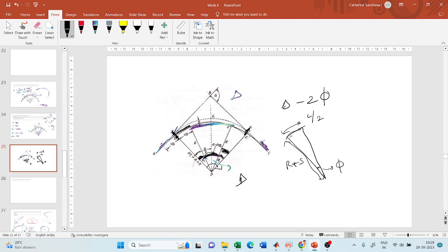You have shift on this side as well as on the other side, so about the center the radius is R plus S by 2, because you need the radial distance to the center of this shift. If this is R plus S by 2 and this is L by 2, I can find out phi, because the length of the arc is nothing but R plus S by 2 into phi.